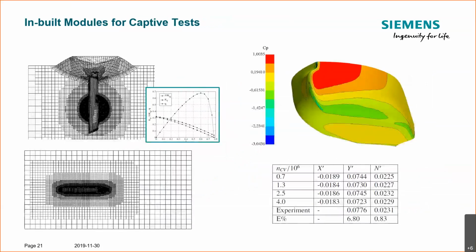So this was the grid that was being used. The virtual disk was applied because there's no requirement here, for this low forward speed and the maneuver we look at, to accurately resolve the propeller flow. We just need the wash over the rudder, basically, which the virtual disk can provide.